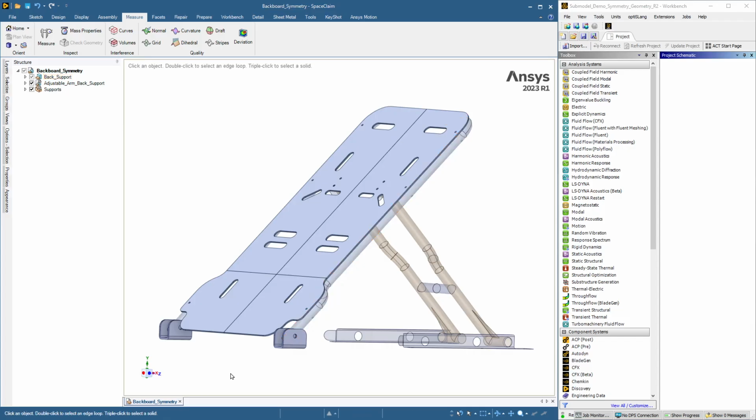And in the second video, I will extract the forces and do a sub-model using this solid portion of the backboard, applying the deformation from the system model to the sub-model and applying the joint force to the hole using a bearing load. So let's get started.